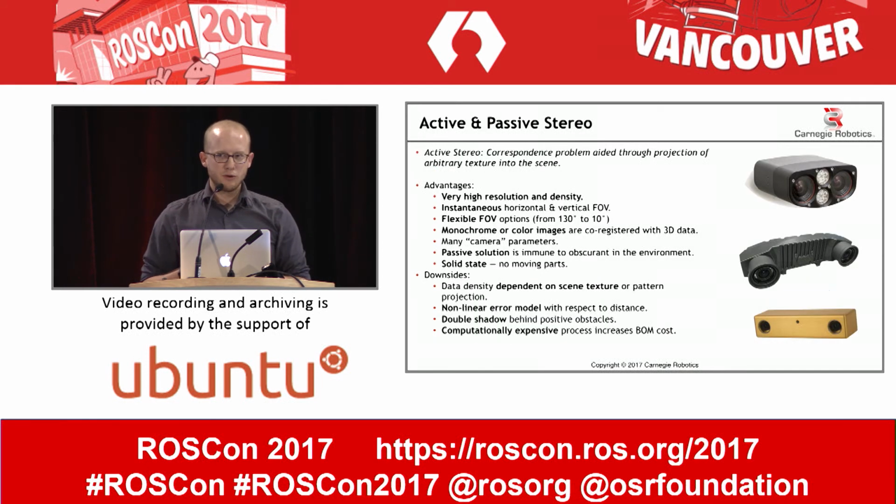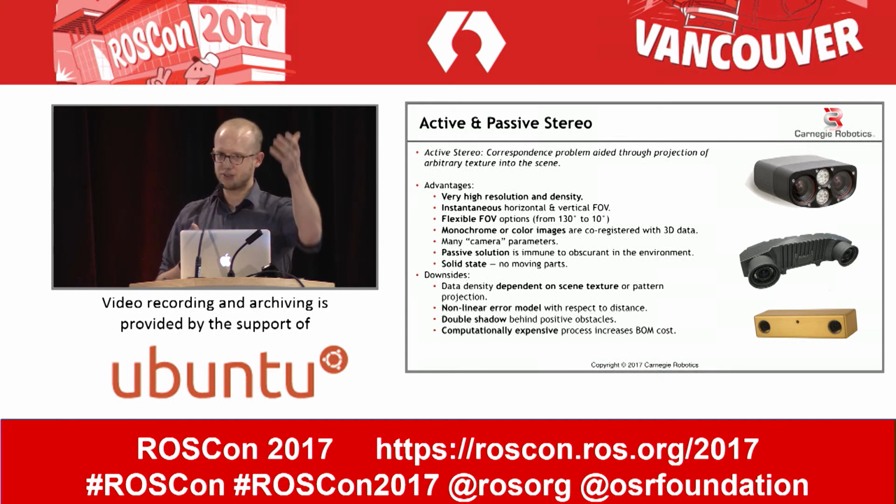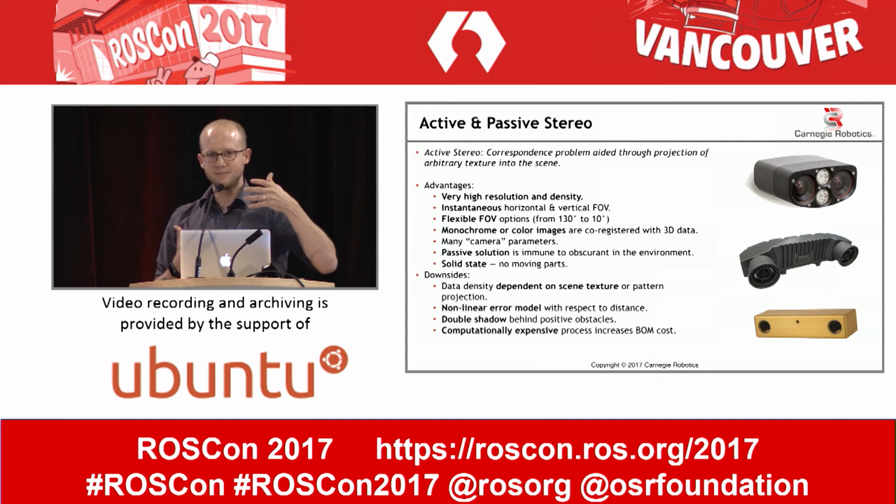The advantage of stereo is that you have very high resolution and density, but unlike these other forms of 3D sensors, their accuracy is limited at range. It's no longer a standard linear or constant error model. It's actually a quadratic error model. And as objects get farther away, the camera's ability to perceive them accurately decreases, just like my ability to perceive the distances to these chairs versus the back of the hall. Distance really affects the accuracy.